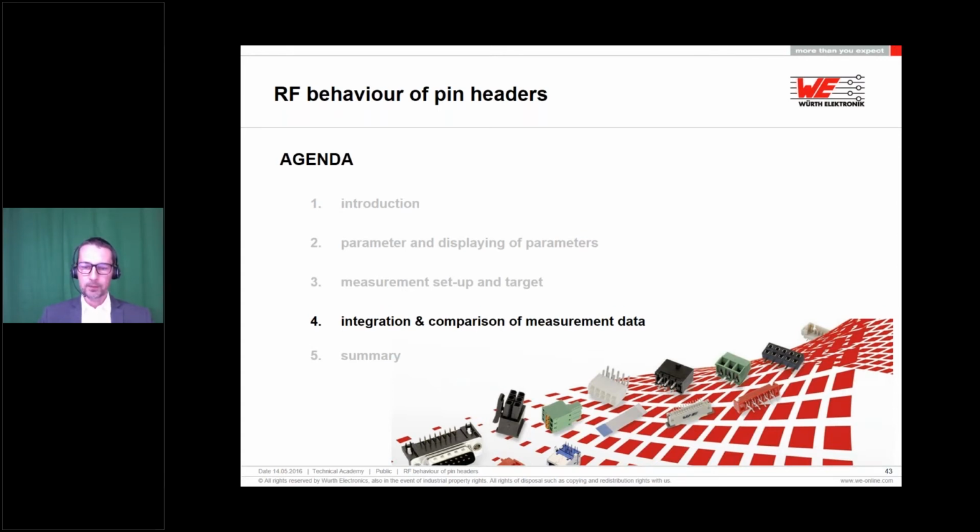And the benefit of this is that we can directly compare our curves in this training, but you can also use this to see what influence the part has on a circuit if you use these data for simulating with LTspice, because even if it's not 100% accurate, it's still a lot better than making 10 test boards in different configurations, check out, make a new one, and so on, which is very time and cost intense.